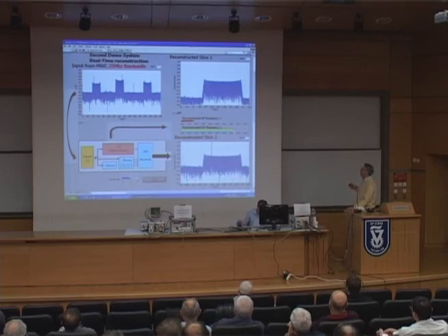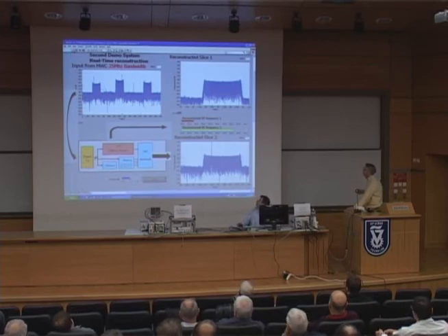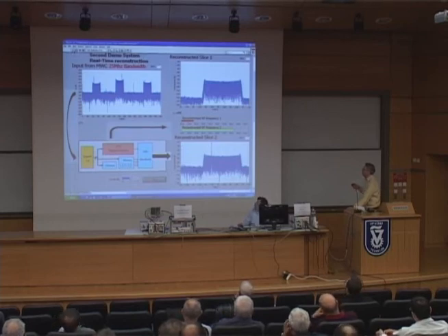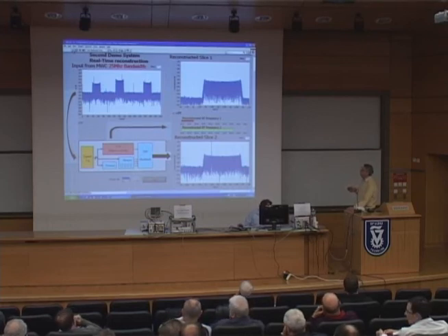And this is the contents of the slice, the FM signal, and here is the sinus signal, and as you see, this is about 40 dB above the noise floor here, and here is nothing to be seen from the sinus signal, even though they have always been in the input signals.